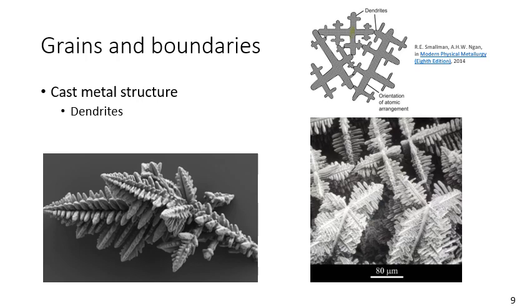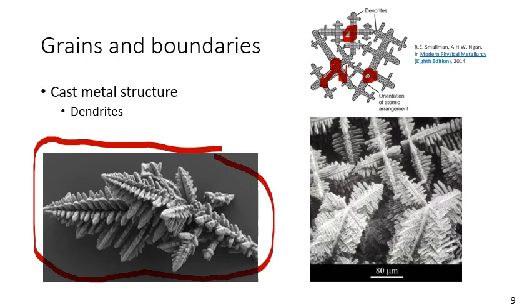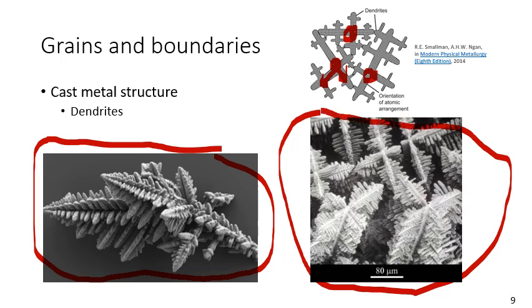So if I highlight in red where the nucleation might have occurred, for the schematic in the upper right here, we see several potential nucleation sites, and then growth occurs outward from those into the liquid. And it forms these dendritic shapes because of the energetically favorable regions for the next solid to form. So you get these beautiful, intricate structures that can form, not dissimilar from a snowflake.